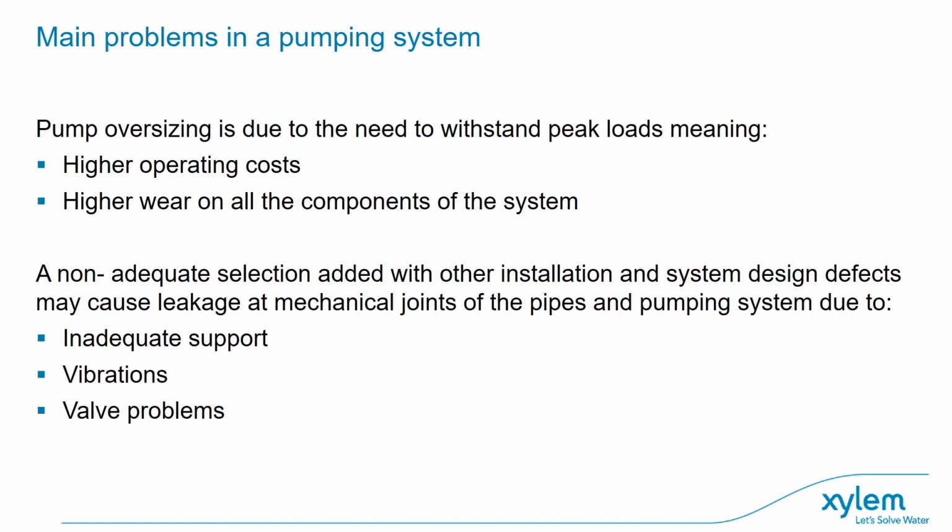displaying the fact that, as we already said, a pump oversized might be due to the need to withstand peak loads. Actually, this means higher operating costs, as correctly already displayed by Paul, higher wear on the pump itself and on all the other components of the system, as excessive flow energy is forced into the system, creating unnecessary wear on valves, piping, and also piping supports.